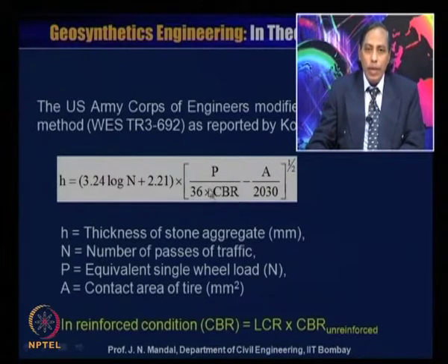Now only this CBR value will change when there is no geotextile material. So you know the CBR value, and when there is a reinforcement, then this CBR value will change. This CBR value is on the higher side with respect to the unreinforced soil, and that's why the thickness of the stone aggregate will reduce. So in the reinforced condition, CBR will be equal to LCR into CBR of unreinforced. So we will see some examples.